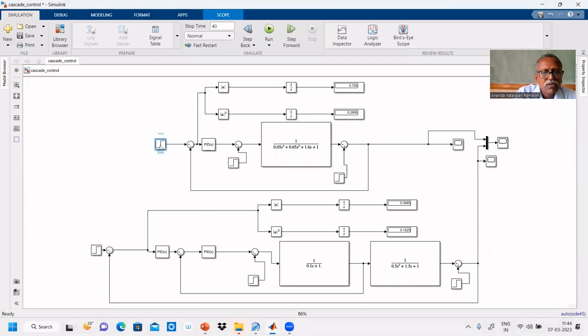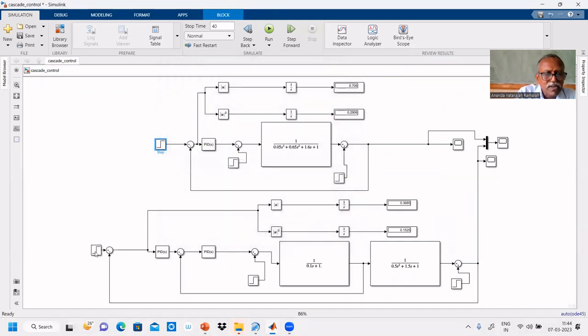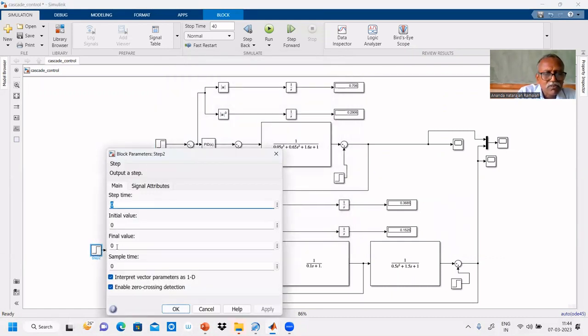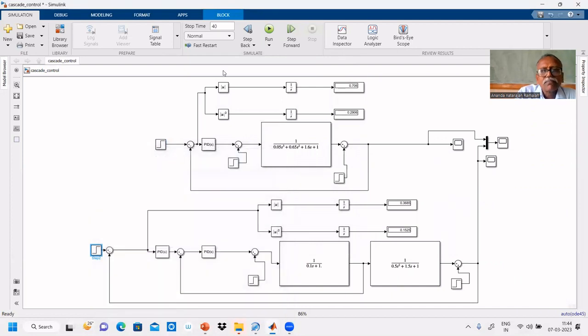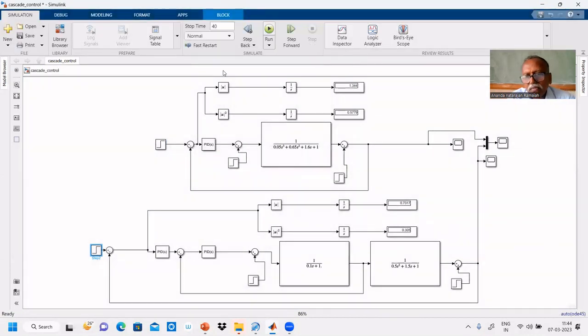Let us consider all together, that is servo as well as regulatory, and both the disturbances. Let us give. If you check ISE and IAE, considering all together, here 1.3 IAE, here 0.7 only. Here 0.57 ISE, here 0.3 only.